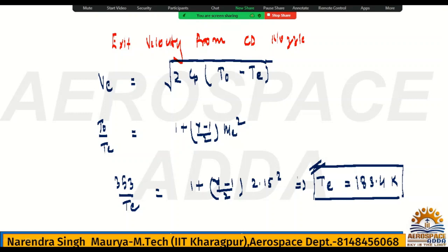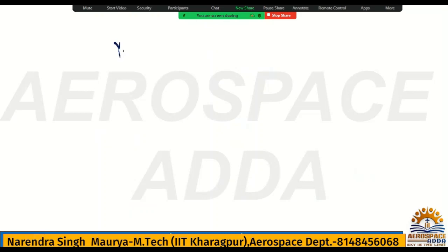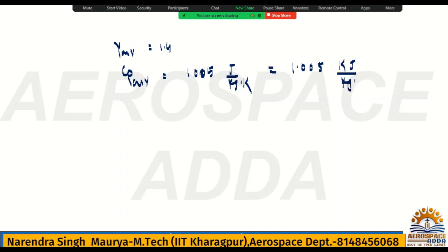All right, now check. So T naught we have, and Cp, because for air you have taken gamma is 1.4, and Cp also you can say it is air. So at that time I told you 1005 joule per kg Kelvin, or also I had said 1.005 kilojoule per kg Kelvin.